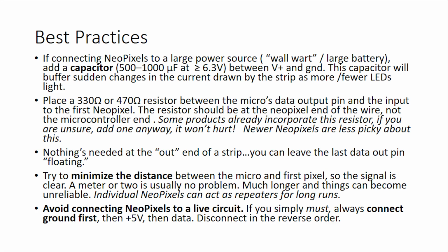And this kind of reiterates the same stuff that I've already said. If you're using a wall wart or a big battery, add a capacitor to stop the step current effect. You need a data resistor between the output of the data pin and the input to the first NeoPixel.